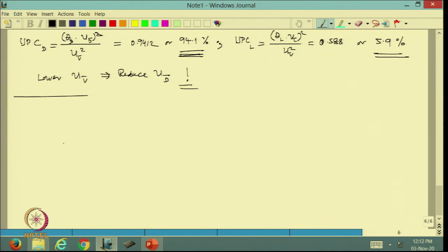But there is another, much simpler way we could have done this, by recognizing that V is equal to pi d square upon 4 into L, which is a multiplicative relation. So, there is a shortcut we can use, and we know that the exponents of d and L will come in the way the uncertainty propagates. And the formula that we had from notes is that